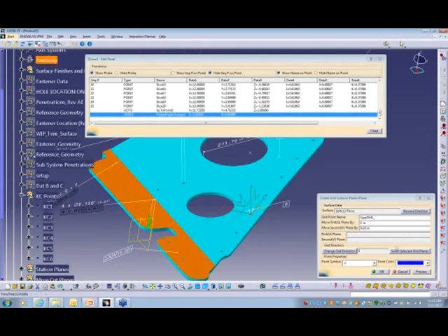We can pick our surface, set the vector. We can say we want our 1 inch grid coming from here and our 1/4 inch grid coming from here. We can do a preview. If we want to put more points, we could change that at any time and say, I need more points on there. I want to do a preview. That's too many. Let's go to the 1/4 inch. So we have full advantage of all the CATIA functions, and we can say OK.